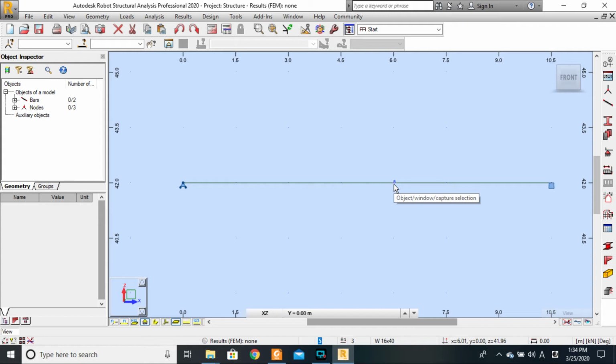You have to understand that a pin is like an internal pinned support, right? It allows for rotation but does not enable translation. In fact, the transfer of displacement is consistent, but the transfer of rotation isn't, okay? Due to the fact that a resisting moment there is not available, or at least in our modeling, it is assumed not to exist.